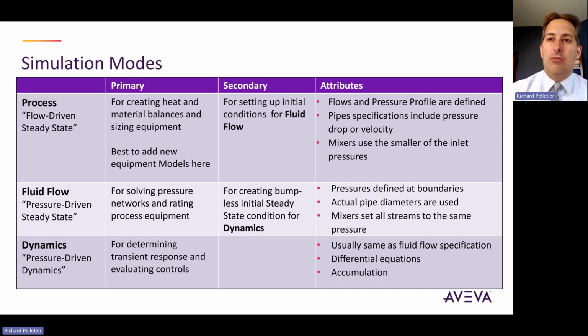All right, so what you'll find a lot of times is that all the models are designed to be implemented, first used in process mode. When you drag and drop them from a model library and you put them on the canvas, the idea that the program will be square and solved at its starting conditions, that all comes from the assumption that you're doing this in process mode, right?